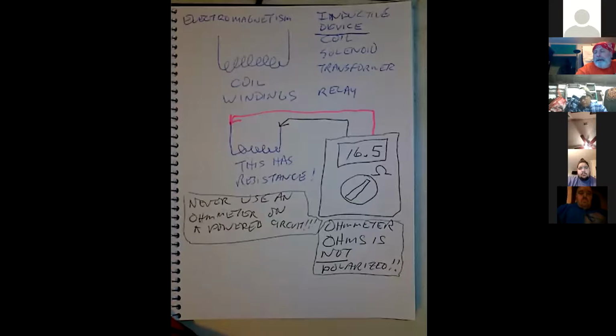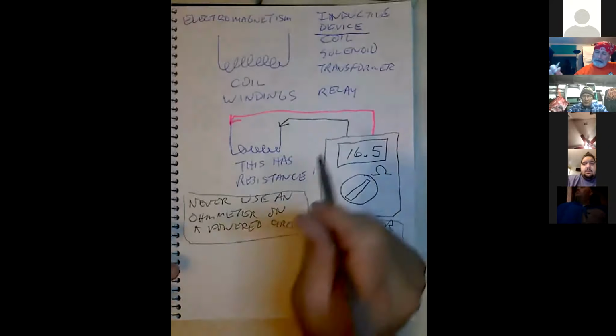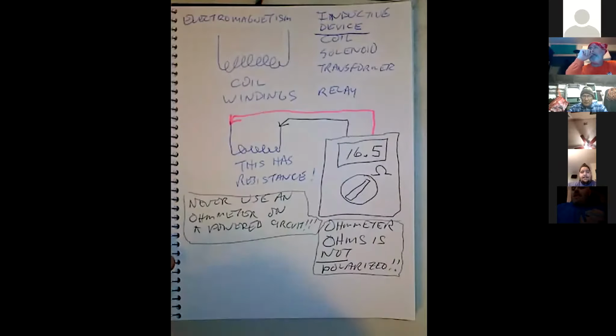Speaking of which, Chuck, how many volts go to that solenoid? Which solenoid are we talking about, fuel injection or the evap? Either one. Depending on the schematic, it should be under 12 volts. All your solenoids are going to be 12 volts as far as I know. It'll be the amount of amperage that's controlled.